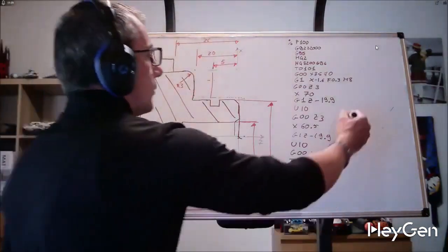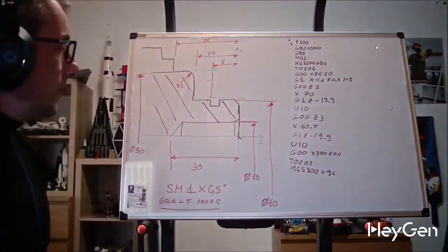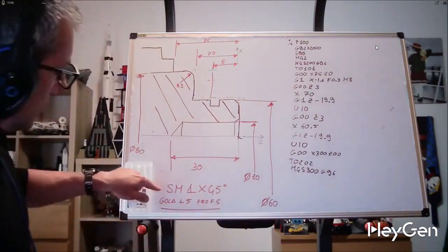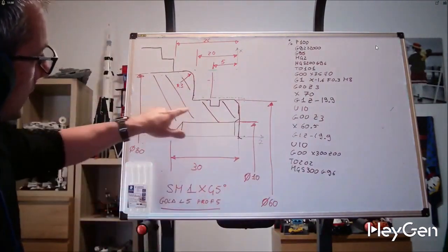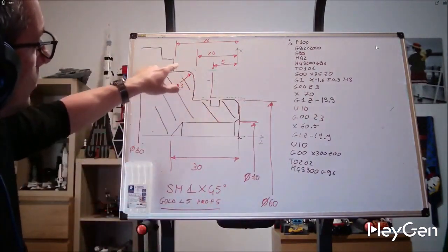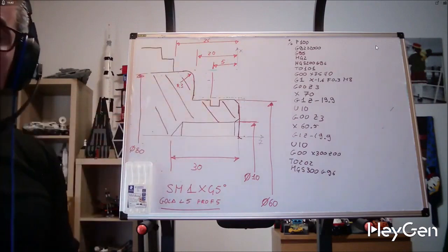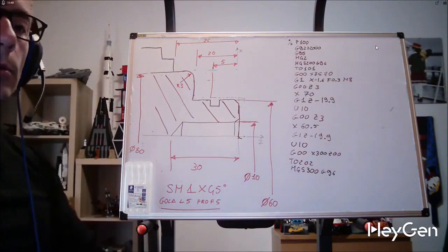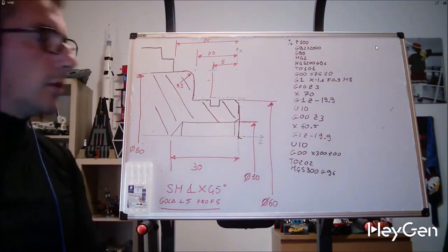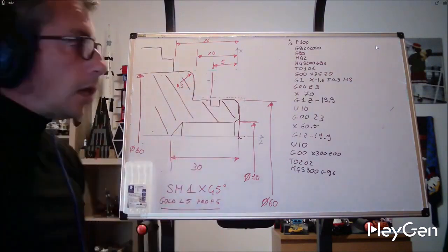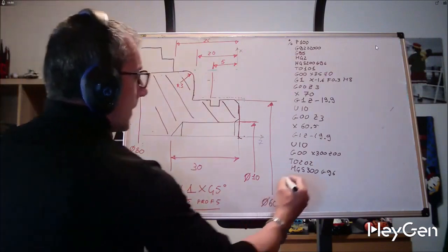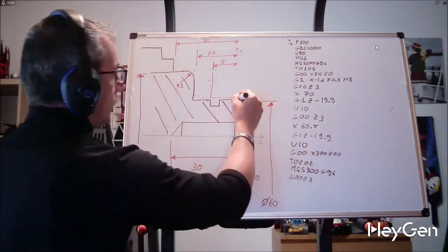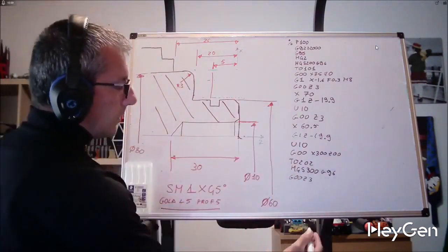Here I move over and do the finishing. I will position myself. So we have chamfers of 45, a cylindrical turning, a radius, and a groove that we will ignore for now. Because to finish we will use a DNMG insert, a VNMG, at 35 degrees and 55 degrees. Obviously, I can't do the groove, so I will go quickly. G0 Z3. This is 59, but we are a bit lower, at X56.